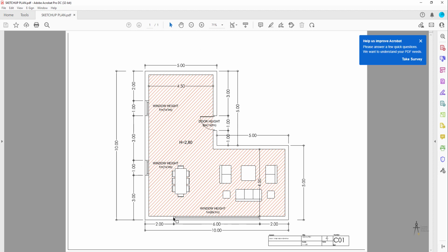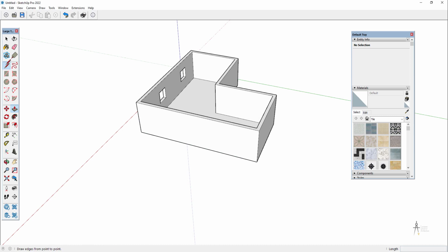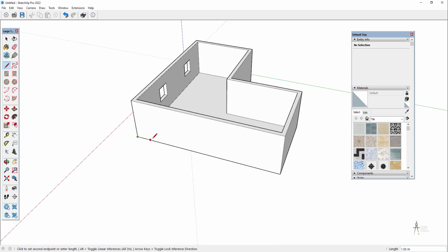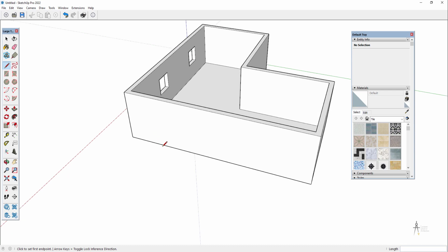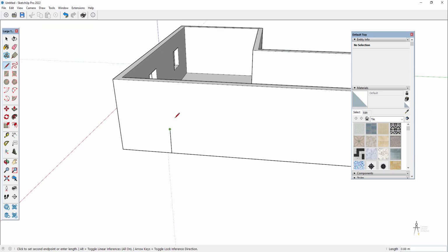As you can see, this window is 6 meters wide and is 2 meters away from this corner. Okay, and it's also a meter away from the floor. So same process, 2 meters here, a vertical line, a meter away from the floor, and now, well, we've got this long 6 meter wide window, 1, 6, and I close.